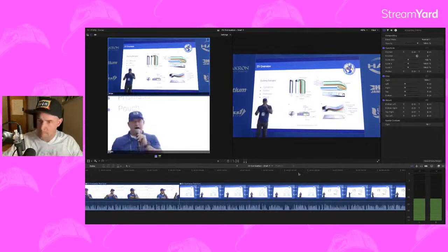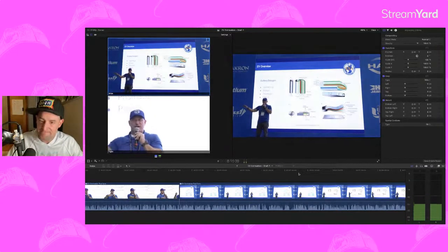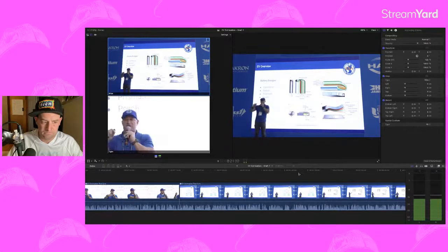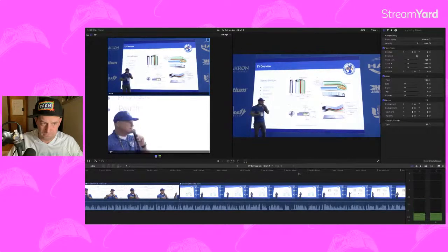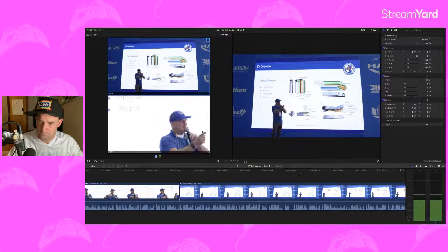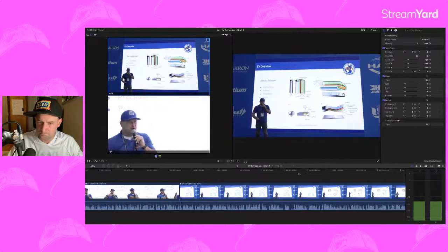Prismatic batteries, predominantly found on much of your European imports, your BMWs, your Mercedes. Same concept, but I'm going to fold up those layers of noodles, and I'm going to slide them into a rigid metallic case, okay? And then I can also have pouch cell batteries. Pouch cell batteries are like metallic envelopes where I'm slipping all those same layers of material into the equation.